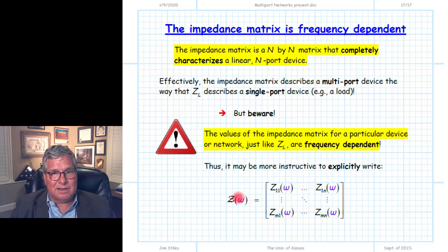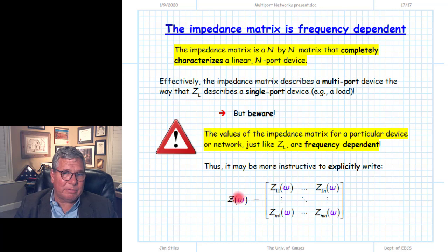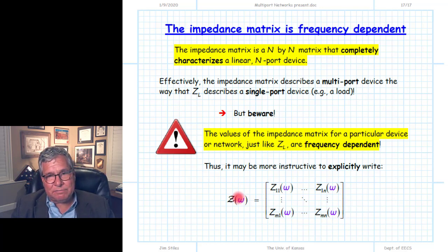Measuring across essentially all, or at least a wide bandwidth of omega, or doing an analysis of the schematic across all values of omega, once we do that, we've really distilled all the information of that multi-port schematic down into a few parameters, the trans-impedance parameters as a function of frequency. They tell us really everything we need to know to do any analysis that involves that multi-port device.